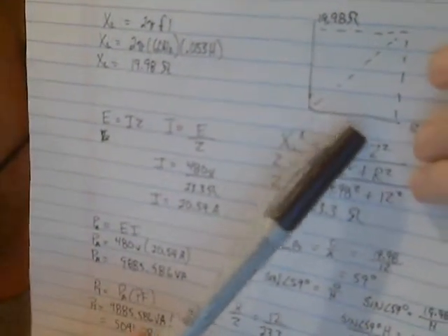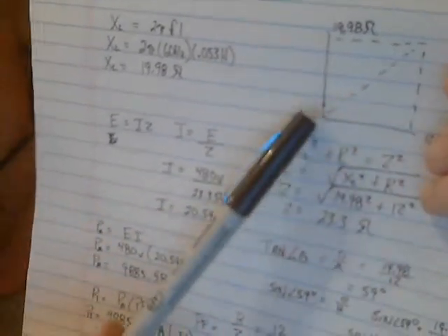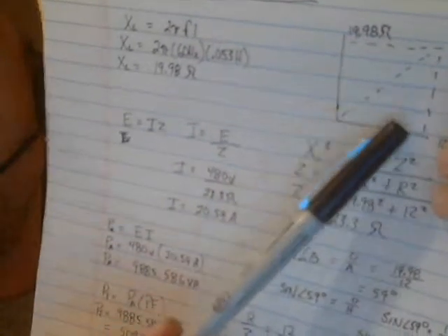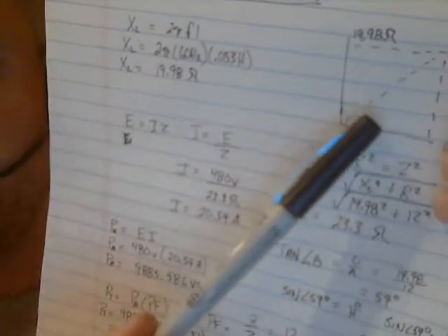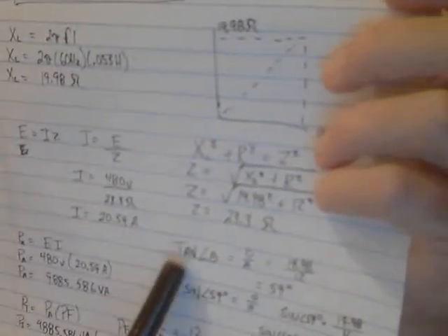Okay, I can check myself by using trigonometry. If you want to go that route, you can take the tangent just to double check your value. Since this forms a right triangle, and remember that in trigonometry you have these different ratios of one side to the length of another side, we can take the tangent, since we know the length of this opposite side, and we know the adjacent side to this angle right here, which is called angle theta, or the phase angle. We can take that and then use it later in our sine formula to check ourselves. So in my calculator, I hit the inverse function, tangent, and then I plug in my numbers.